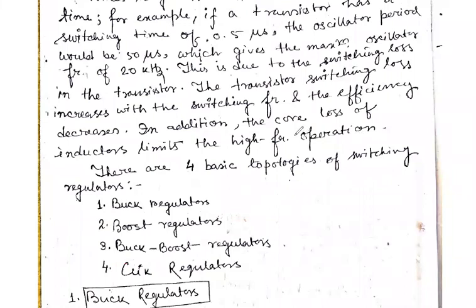The transistor switching loss increases with the switching frequency and the efficiency decreases. In addition, the core of the inductor has some losses, and this limits the high frequency of operations.